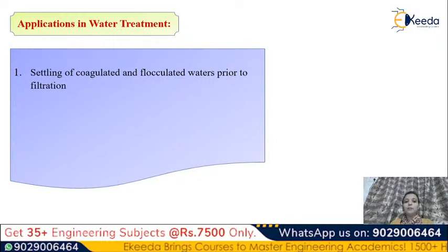So what is secondary treatment? Coagulation and flocculation. Basically, we are providing coagulation and flocculation treatment for removing the dissolved particles that we cannot remove in the primary sedimentation tank. So what are we doing in the coagulation flocculation process? We are adding some amount of chemicals in the coagulation flocculation chamber and mixing it at very high speed. Because of that, all the dissolved particles present in the water collect or agglomerate to each other, and there will be the formation of floc.